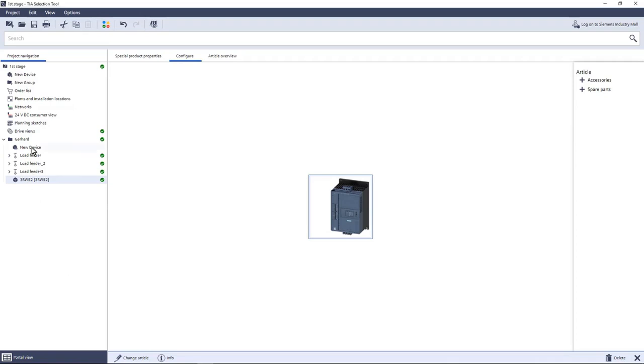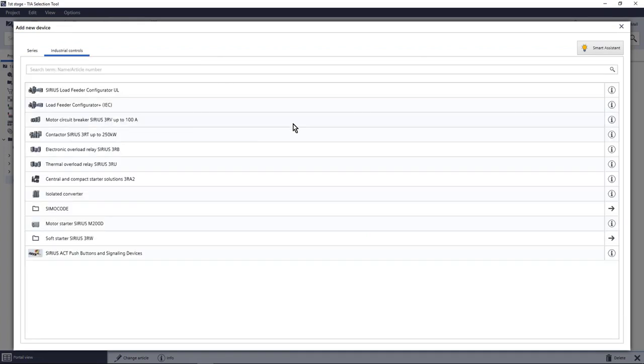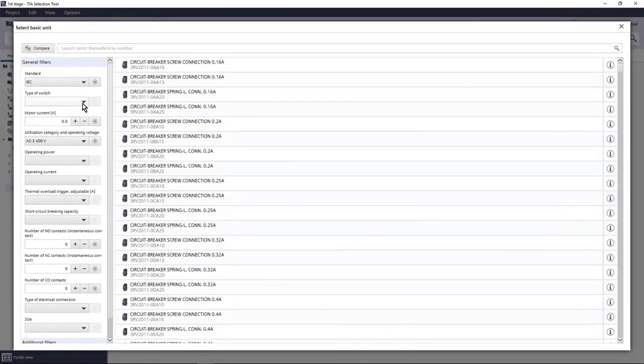Then we have the selection here in a really easy way, and as I was saying, here you will have the soft starter, and now it's included in your project. Okay, now the second stage for this will be the selection of the breaker of the MSP that we actually want to use here.